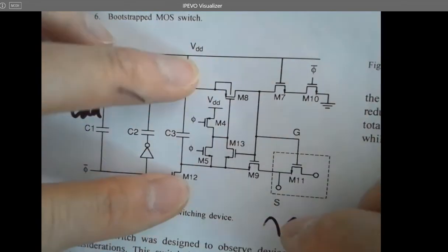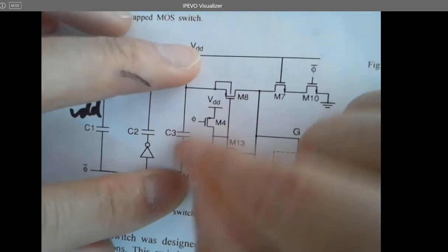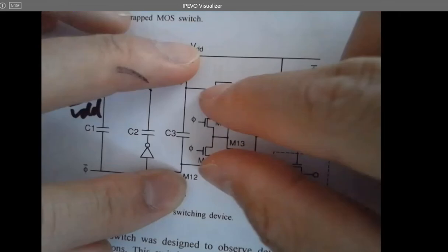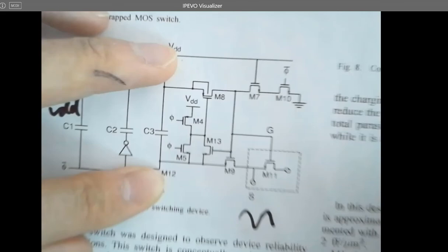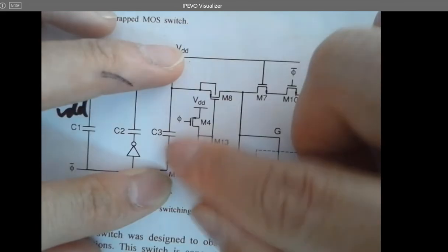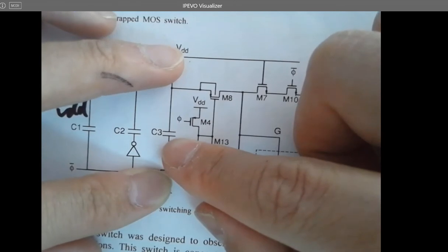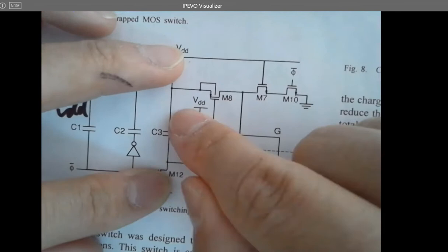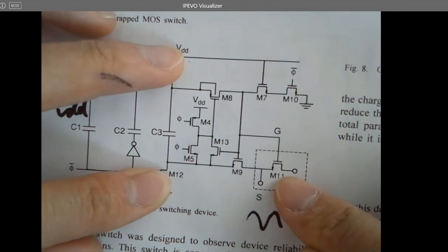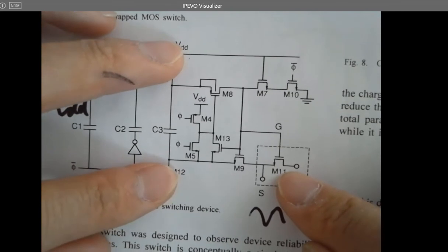So as the next cycle, these two transistors are gone and only leave this capacitor floating in the air. This is not being connected to VDD or ground. It's just floating there and holding a VDD voltage across the two plates. Nothing else. Just floating. So whenever it's floating, and whenever you're adding or subtracting a signal to it, it's going to track that signal. All right. So now let's see how it tracks that signal.